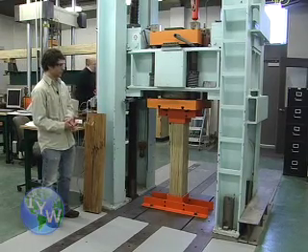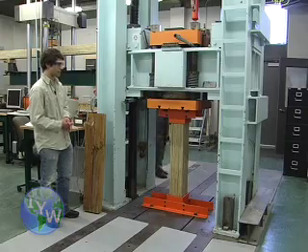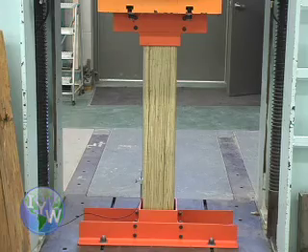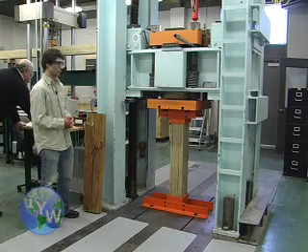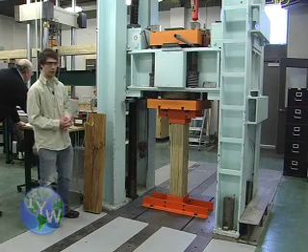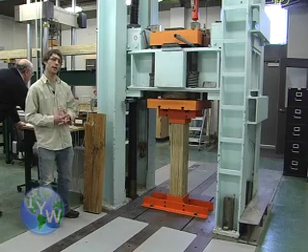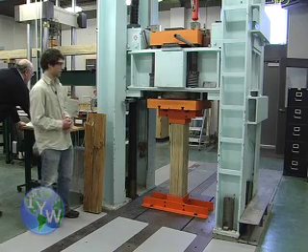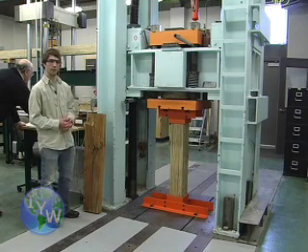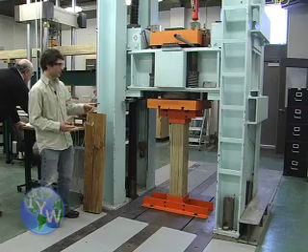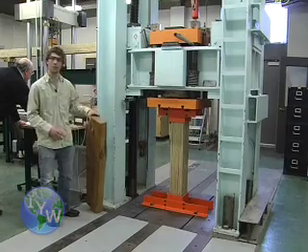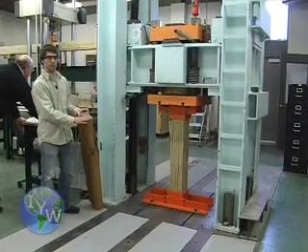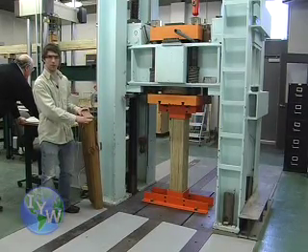But this material that we have in here is basically aspen, different Populus species. And from the Wood Handbook, we find that 120,000 to 250,000, those numbers make sense for this size of member. Now this is about 50 square inches in cross section, whereas this piece is about 30 square inches in cross section.